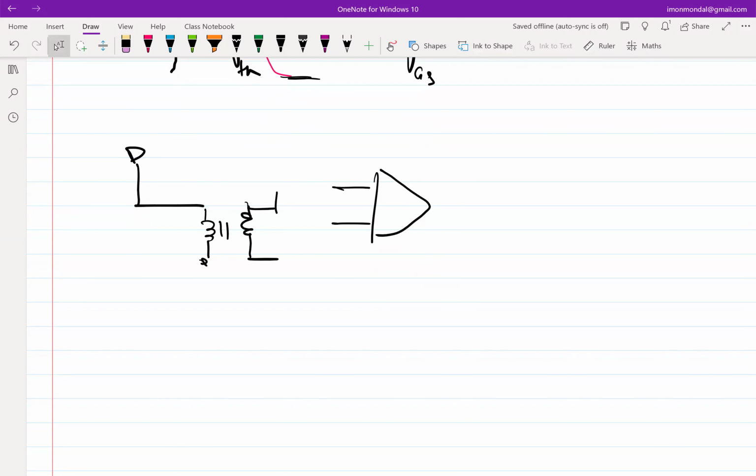If they are perfectly balanced, then you are going to get, say this is VI, based on the turns ratio, I assume the turns ratio is 1 over root 2, or root 2, in that case you are going to get VI by 2 and negative VI by 2, right? Similarly, you can play around with the turns ratio. As long as the output phase is differential, it's all good, right? So then you have a differential way of getting the signal through.